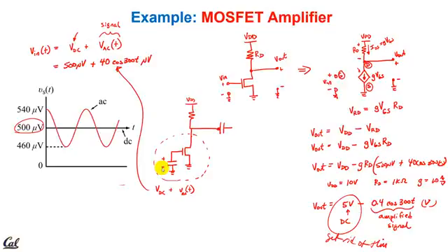So one thing that I would do is take advantage of the fact that we have a VDD in our circuit, from our battery or wherever it comes from, and just put a couple of resistors there, make a voltage divider, right? Yeah, exactly. So a very common thing to do, I'll reproduce this thing. So this is the original thing, and here's ground. You actually build some resistor circuit that gives you a DC point between ground and VDD. Call these R1 and R2. And then your signal comes in here, and then you run that to the FET. Oh, okay. So we can set the DC level there by picking R1 and R2. It's just a voltage divider.